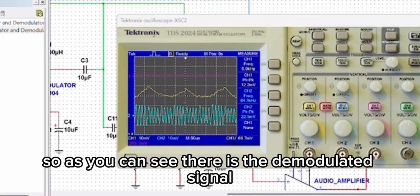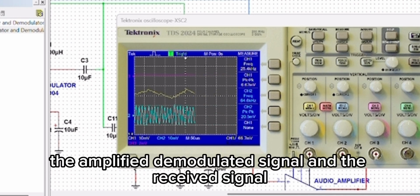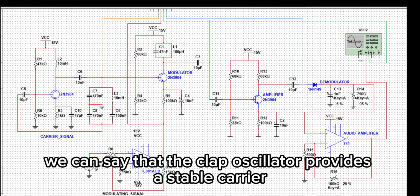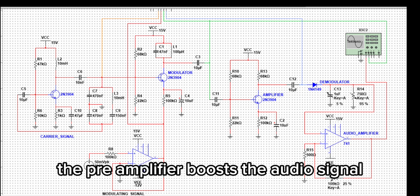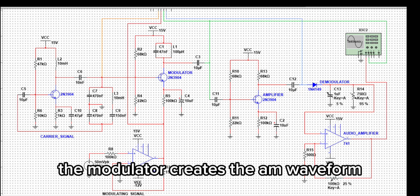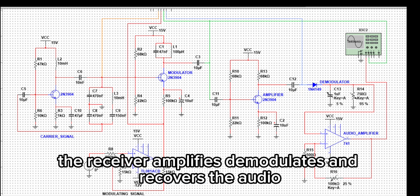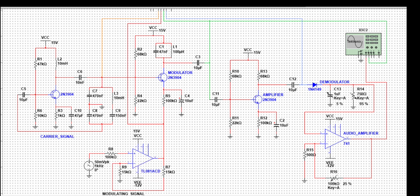Meanwhile, here is the demodulated signal. So as you can see, there is the demodulated signal, the amplified demodulated signal, and the received signal, which is the modulated signal. To conclude, we can say that the Clapp oscillator provides a stable carrier, the preamplifier boosts the audio signal, the modulator creates the AM waveform, the Class A amplifier strengthens the signal for transmission. The receiver amplifies, demodulates, and recovers the audio.